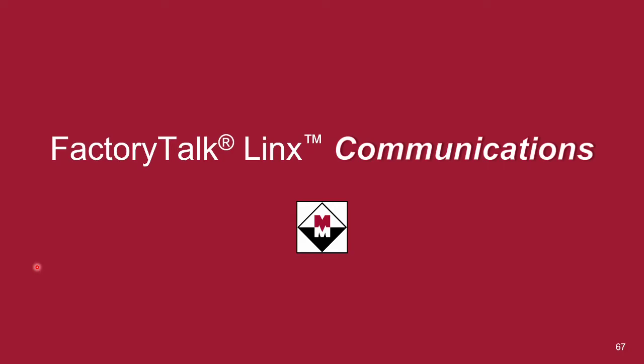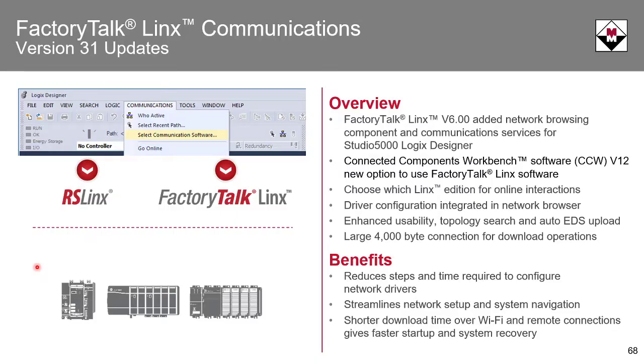So I'd like to talk about a couple of other additional items. FactoryTalk Linx communications. In FactoryTalk View Studio version 10, RSLogix Enterprise became FactoryTalk Linx. So when version 31 of Logix Designer came out, they added an option to choose FactoryTalk Linx as your communication software.